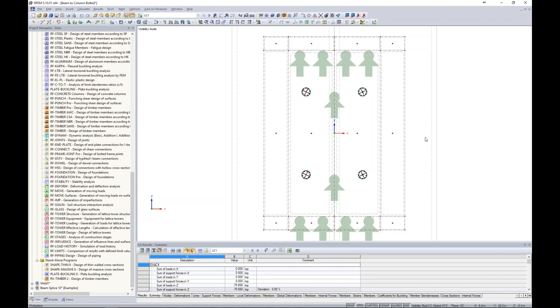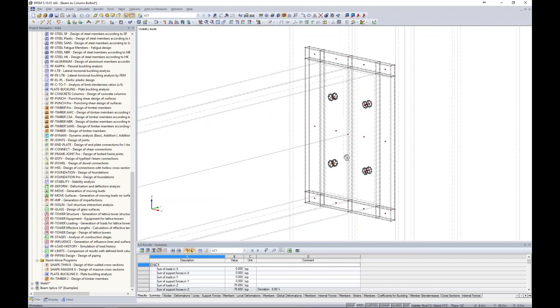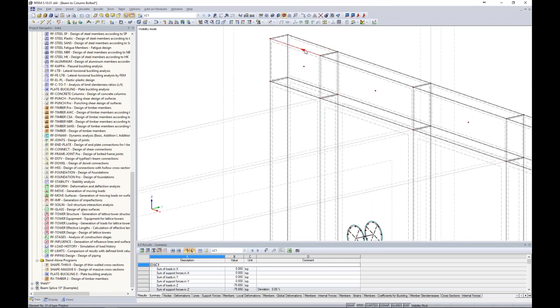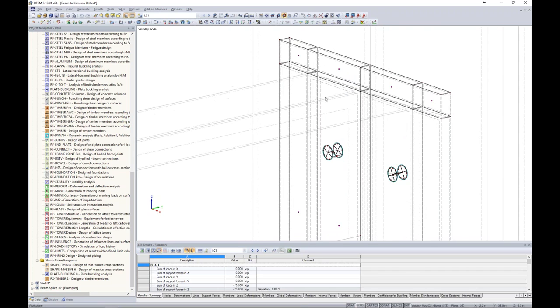And the reason for this is simply because I didn't have so much symmetry like we did in our last model, so I had to create these smaller contact solids in order to meet the requirements. The requirements being that each contact solid must be comprised of 4 different lines, as well as contact solids must have identical integrated objects on surface A and surface B.